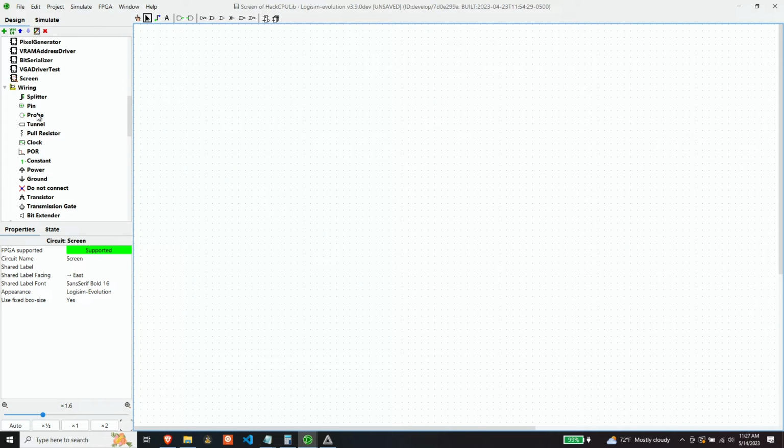First thing is, of course, we'll need the clock. Now the next thing defined is a load flag, because this component, from the perspective of the CPU, just looks like memory. So it needs to be able to load memory. The CPU needs to be able to read a value out of memory, and with the load, it needs to be able to write a value into memory. So this I/O interface looks basically just like a RAM component, with some additions we'll talk about in a second.